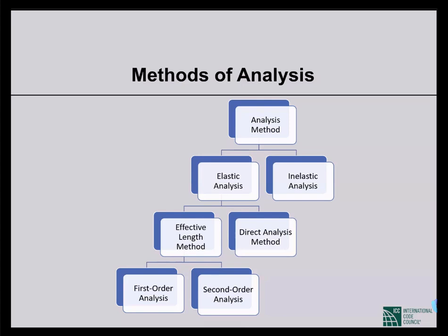First order analysis, that is usually the analysis we prefer, that is elastic, completely elastic, without any kind of inelasticity and without the consideration of p delta effects, etc. The normal stiffness method type of finite element method, where superposition is valid. That type of analysis is first order analysis. And another is second order analysis, where we modify the first order results and consider the second order effects. That's second order analysis.